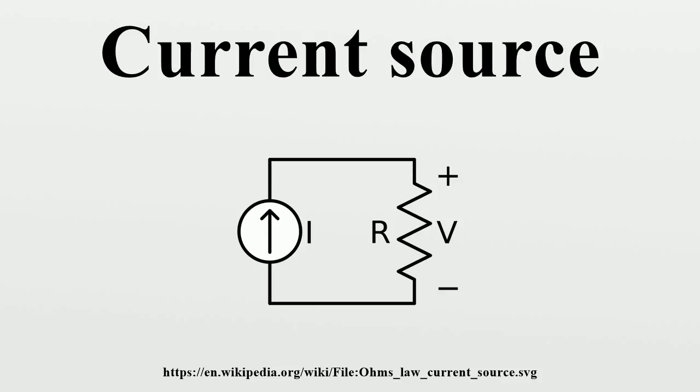As long as the temperature remains constant, the load current will be independent of the supply voltage, R1, and the transistor's gain. R2 allows the load current to be set at any desirable value and is calculated by R2 = (VZ - VBE)/IE, since VBE is typically 0.65 V for a silicon device. Resistor R1 is calculated as shown, where K equals 1.2 to 2, and HFE is the lowest acceptable current gain for the particular transistor type being used.